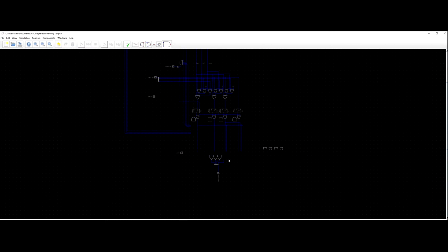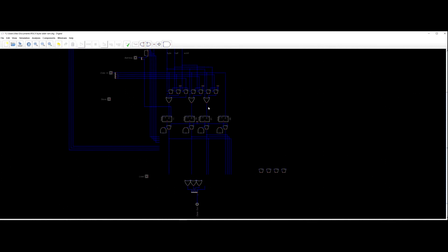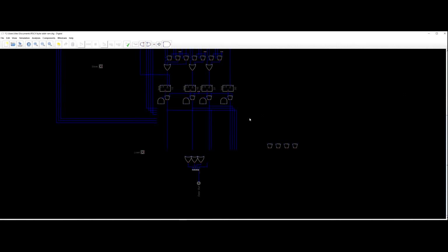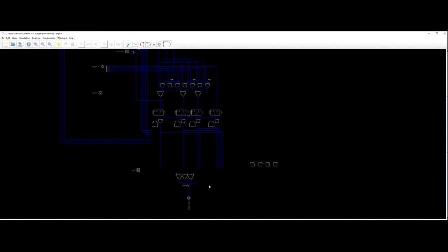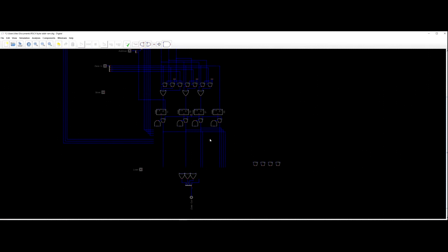Does that make sense, David? So if I think this out loud, the reverse logic of the input is, if I'm asking for a byte out, I can get a byte out of this one, this one, this one, or that one, and I have to put it at the low spot. If I ask for a half, I can get the low byte here, and the high byte would have to be here, or the high byte would have to be here, and the low byte would be there. So that would bring the low byte over here and the high byte here. And then if I'm writing a word, the only way to get a word to the output is that 1 0 goes there and 1 1 goes there. So I think that makes more sense.